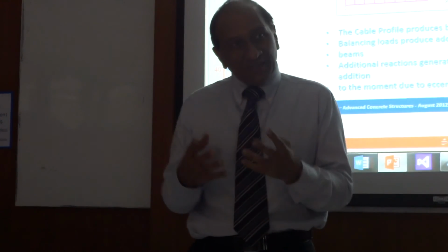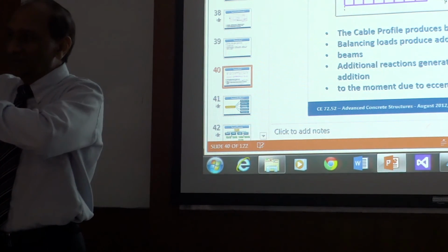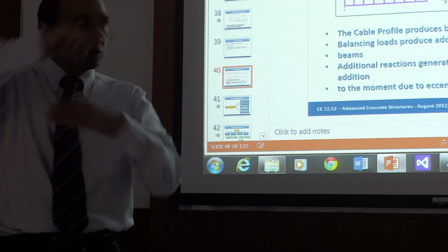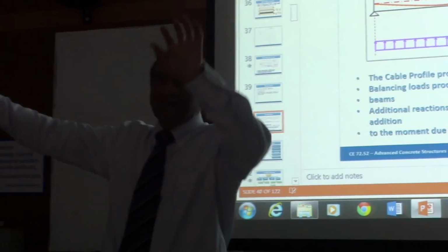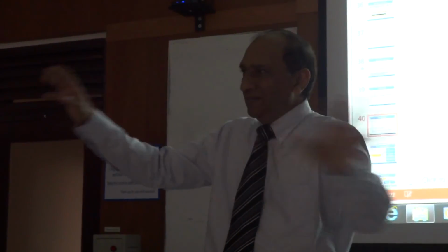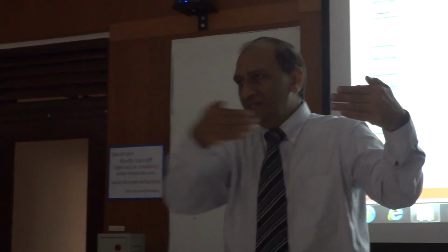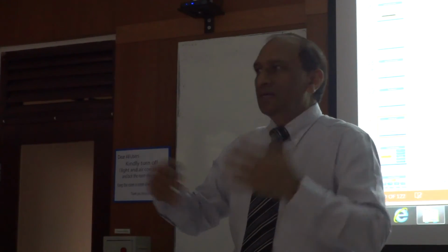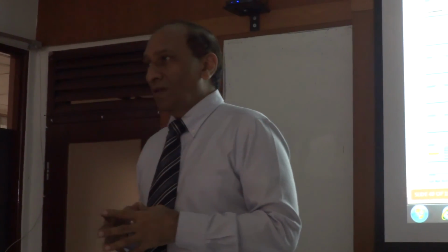Now the advantage of this is that you can combine this in many different ways and sequences, right? This loading is one loading, you keep it separately. Then you bring live load, then you bring dead load, then you bring earthquake load. You bring whatever loads you like, and you combine them the way you want, based on the sequence of the loading. Loading comes first, pre-stressing later, or pre-stressing first, loading later, live load with this, not. So it's just now a combination game, right?